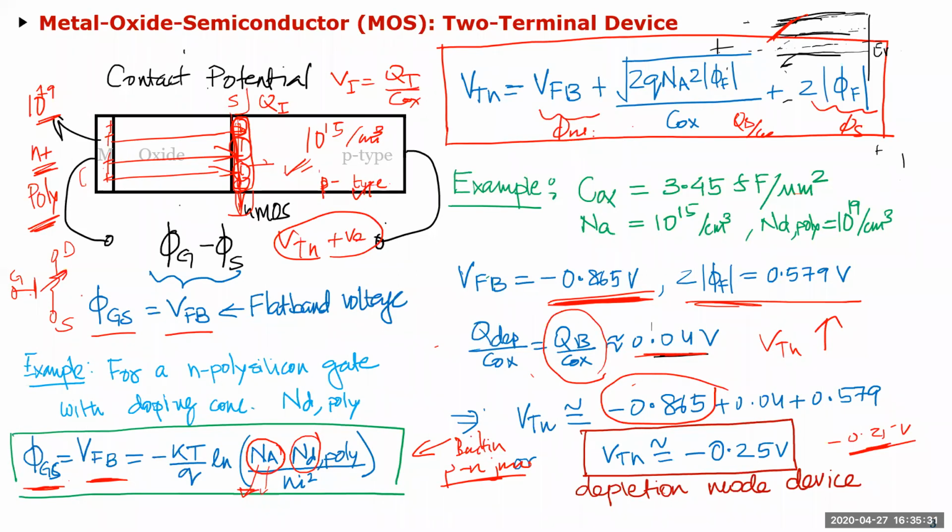It fractures into the silicon and gets lodged into the silicon. But the problem is it breaks your silicon lattice, so you have to heat it, which anneals it and makes the lattice perfect. But like I was saying, if you have any metal there, it will melt. So that's why they don't have metal gates.